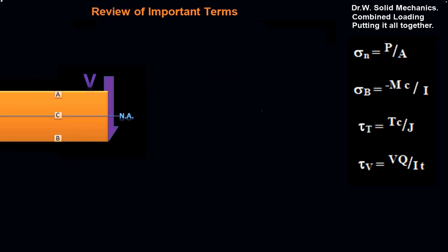If we look at a shearing stress being applied to a beam, we can see that there'd be a shear force here generated at the center, tau, and it will be 0 at the outer fibers. And that occurs because tau is a direct function of Q, where Q is defined as the first moment of the area beyond the cut. So if we have a cut up here, we're talking about this region right there, and our Y bar would be the Y bar distance to its center.